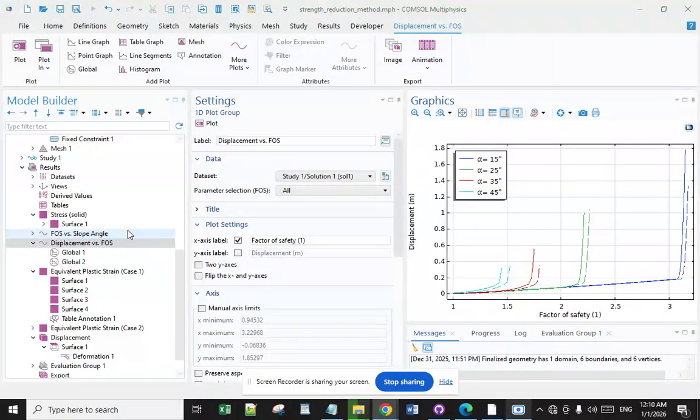The margin of safety is sometimes but infrequently used as a percentage. For example, a 0.50 margin of safety is equivalent to 50% MS. When a design satisfies this test, it is said to have a positive margin, and conversely, a negative margin when it doesn't.